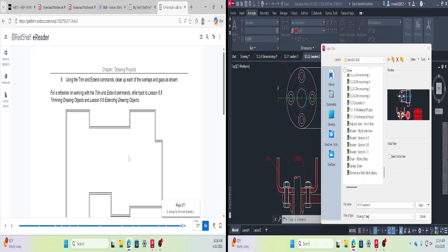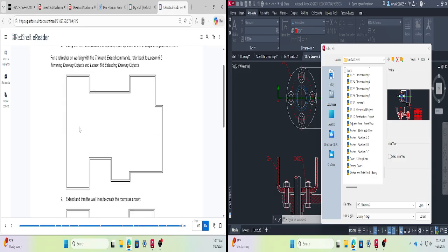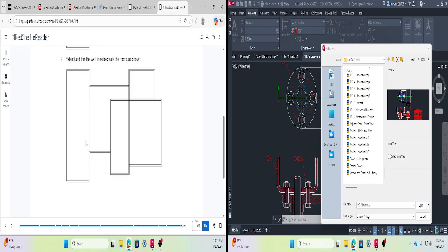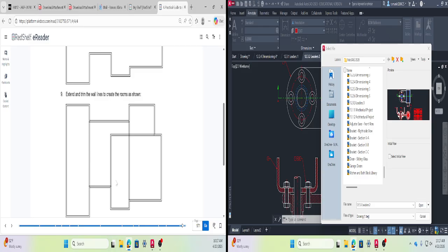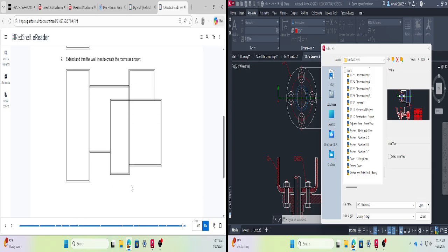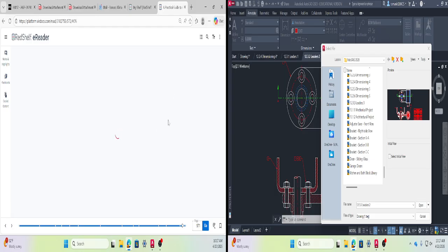And in your project, you may want to do it, and then you'd be using the trimming option, right? There are different trimming options we learned, right? So this is really helpful for your project, okay? As you can see, it clearly shows you how to do the floor plan in a formal way. And then after the trimming, you have a nice looking layout like this with 2 layers. Meaning you have the walls already, then you keep doing the same thing for the interior walls, right? Meaning you would like to add those other lines, offsetting it, trimming it, extending it, and basically get what you would like for your final layout.